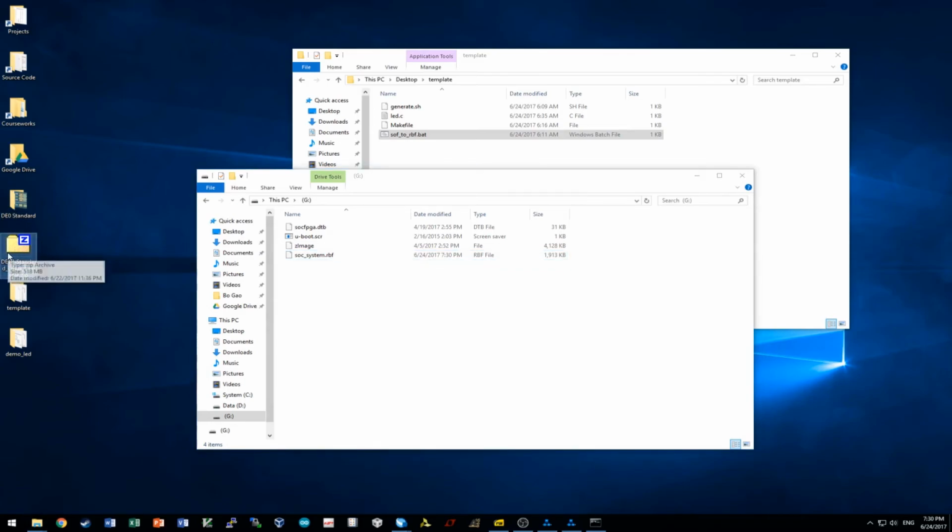If you use the LXD version, it will not boot because it expects some other devices. As I said before, it expects a lot of other devices on the AXI bus, which we don't have. We have a fairly simple Qsys design. So in this case, we have to use the DTB provided with the console version of the distribution.